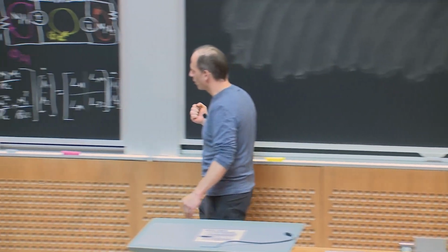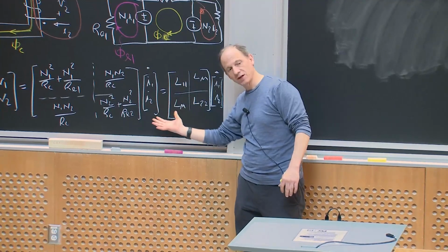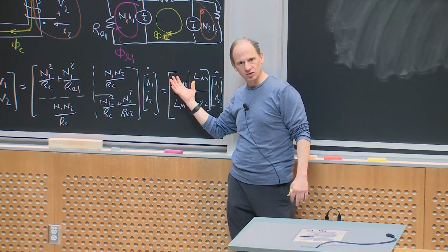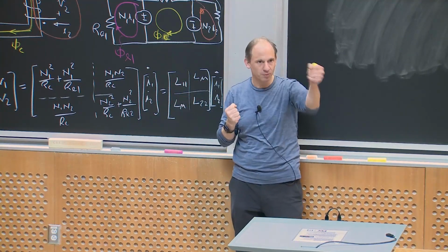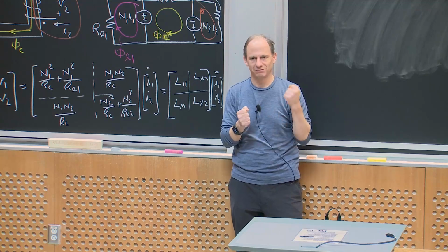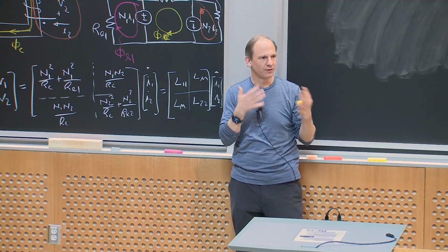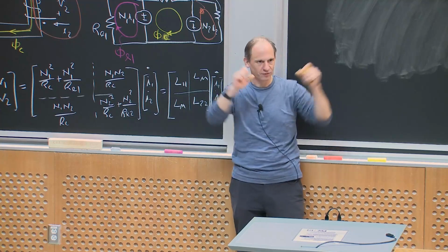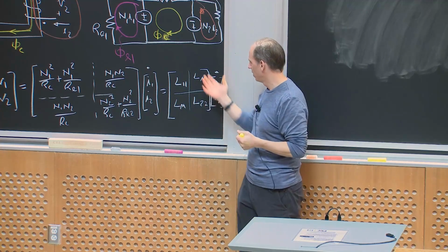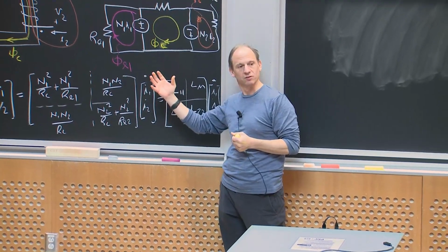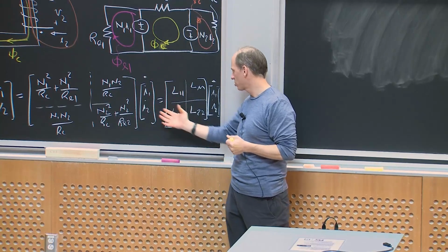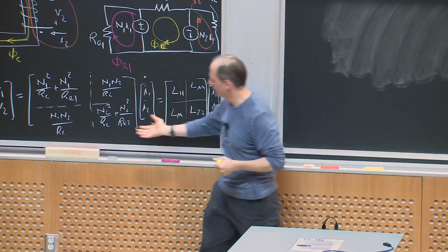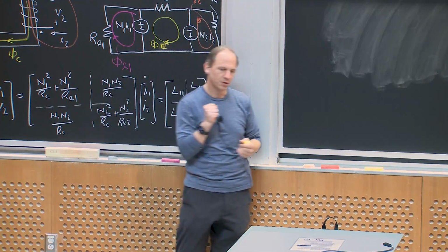And that worked out to look like an inductance matrix, right? So if you have an inductance, that's kind of one parameter that models everything. If you have a 2-port structure, 2 inputs, 2 outputs, or 2 different terminal pairs, then you get a 2-by-2 matrix, okay? And the matrix turns out to be symmetric, as you can see. We derived this in class, okay?